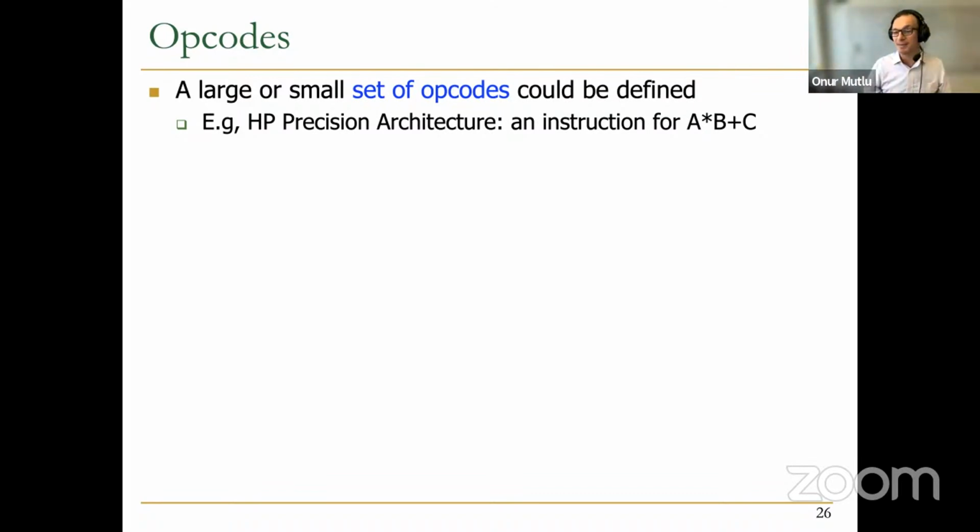And we string together many of them. And they said, if we had a multiply and accumulate instruction that does multiply plus add, then we could actually make it easier for the compiler to map the high-level matrix multiplication code, and scientific code also, into this. And this is actually quite a reasonable design choice. But another design choice is basically, I don't have this. This is more sophisticated than an add and also a multiply, right? It combines both. So this is a choice that's made by the ISA designer in the end.